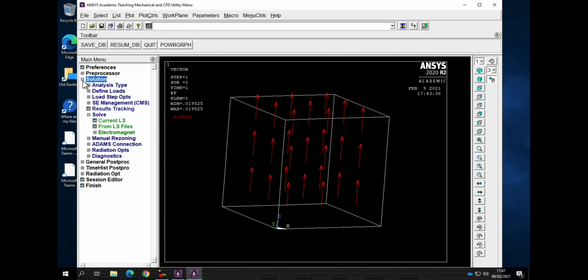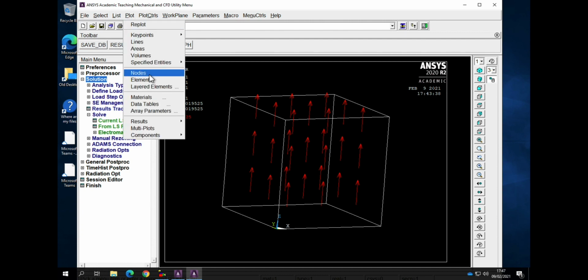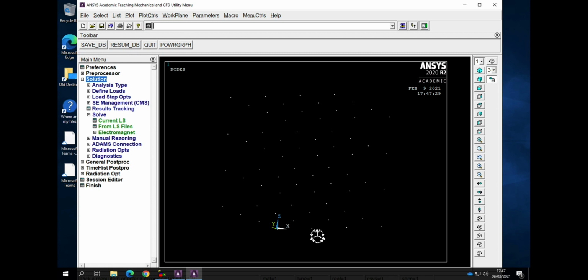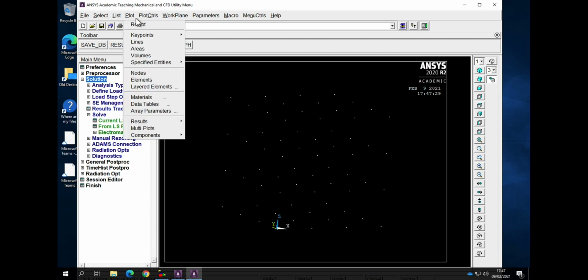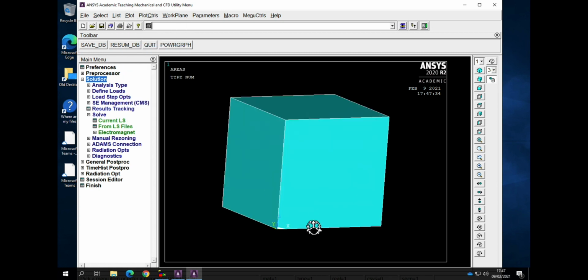I never really do this in a way. I always like to start from scratch. But if I plot my nodes again, so remember at the bottom, let's just plot the area, maybe it's easier. Remember at the bottom I had 0 volts, and the top I had floating, and that was open circuit, and it was settled. So if I imagine now a situation where I short circuit my model, what I'm going to do now is set the top at 0 volts as well.